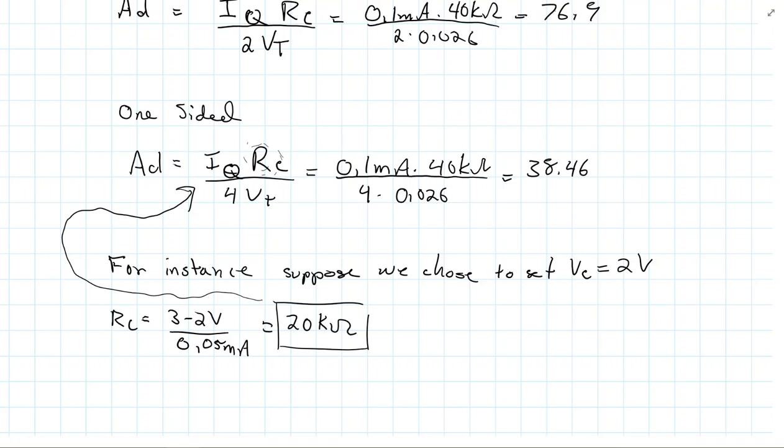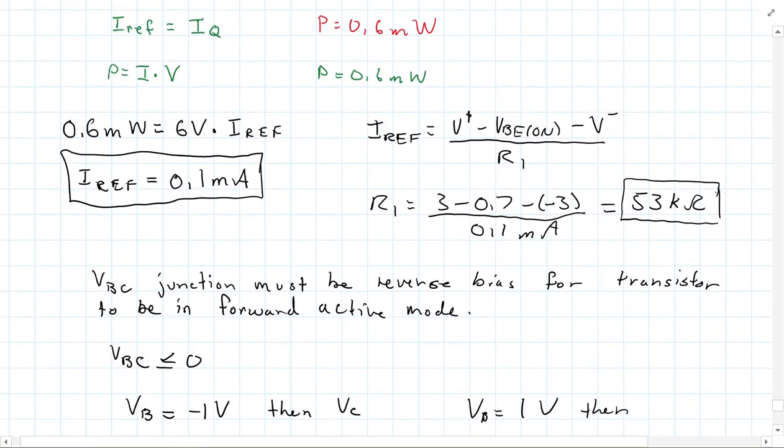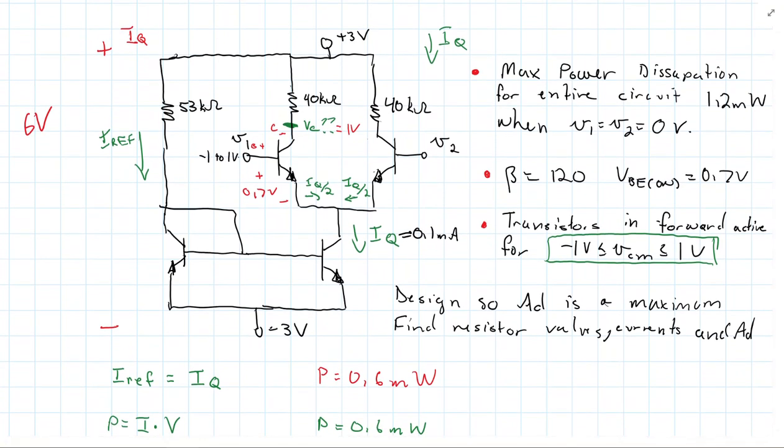So again, if you think about what we're going to need for an op amp, believe it or not, we're actually pretty close to a basic op amp just with this circuit right here. All we would need to do is add on a gain stage and then an output stage. And the output stage would basically be to lower the output impedance of the amplifier, because op amps tend to have a relatively low output impedance. And there's reasons for that, of course.